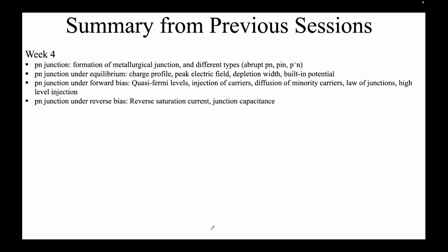Finally, we put this understanding to use to see how a device actually works. Till now we were only talking about semiconductor physics, that is the concentration gradient and the density of states, the drift, the diffusion, generation, recombination. We took a device and applied these concepts to see how that device will function, and we took a very simple device called the p-n junction. That is two semiconductor pieces, one p-type doped and one n-type doped, that is acceptor type and donor type, and we bring them together.